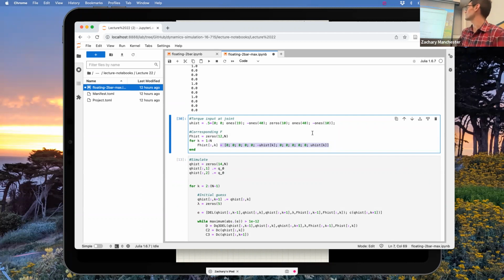So one thing to note, right, is I'm applying this at the joint. So applying forces is a little weirder in this context, right? I don't have a coordinate in there for the joint. So I've got to do that virtual work thing, right? And get the matching Jacobian. In this case, the generalized force is expressed in joint coordinates, right? It's expressed on the joint. So I have to do the Jacobian that maps us from that into these maximal coordinates, right? That's basically what's going on here.